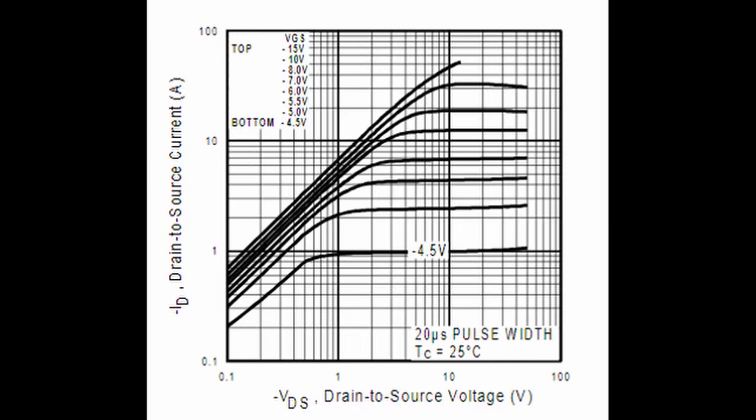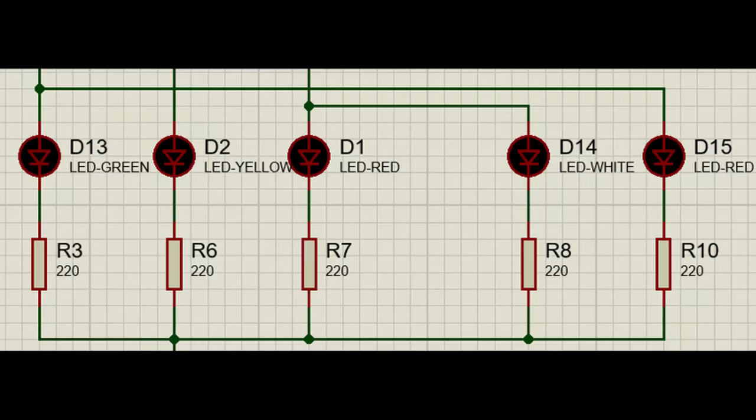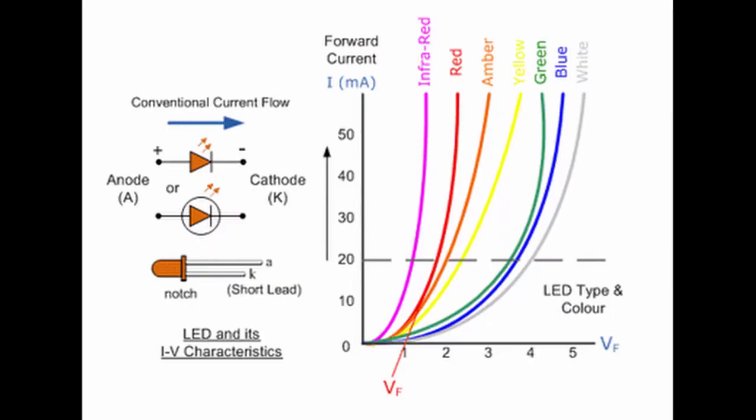Cheaply available LEDs that emit red, yellow, green and white were used to represent the signal lights. The 5 volt might damage the LED lights, as the LED is connected in a forward bias condition across a power supply. It should be current limited using a series resistor to protect it from excessive current flow. LEDs shouldn't be connected directly to a battery or power supply, as they will be destroyed almost instantly because too much current will pass through and burn them out.